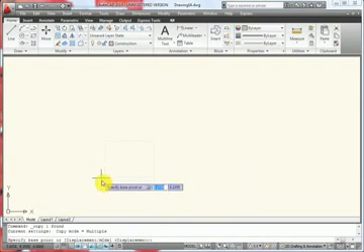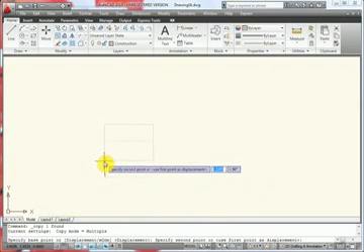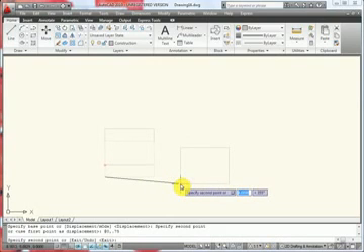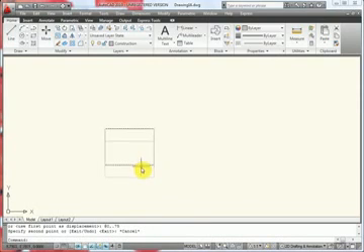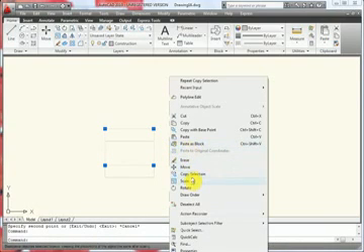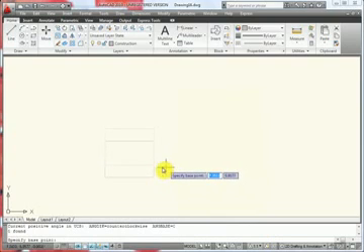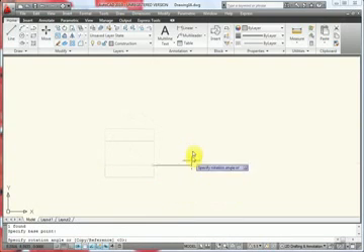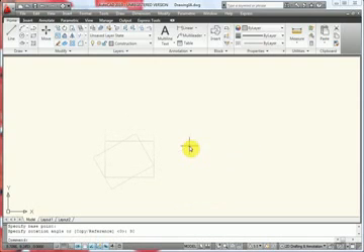I'm going to left click that, choose a base point, and we want to offset it with relative coordinates of 0, 0.75 spacebar. Press the escape key to exit the command. Now I want to rotate this top block down 30 degrees. So I'm going to choose this rectangle, I'm going to right click in the graphics window, and left click rotate. I'm now going to choose a pivot point, which I'm going to use as this intersection between this rectangle and this rectangle at the lower right hand corner. And I'm going to input an angle of 30 degrees. Enter.